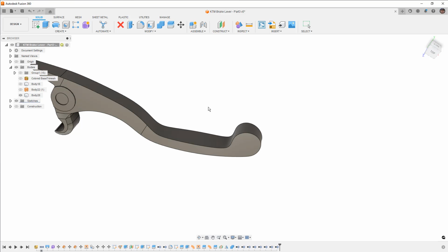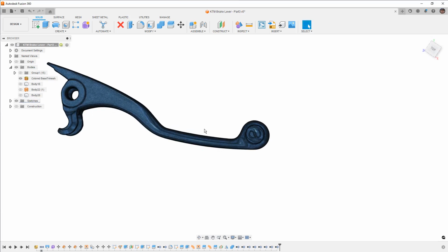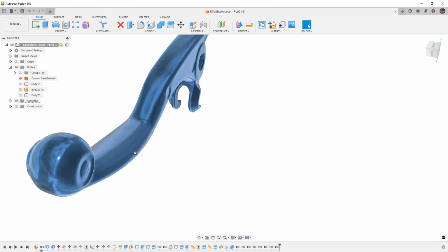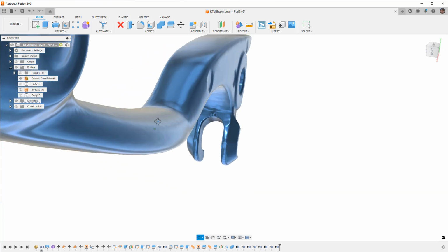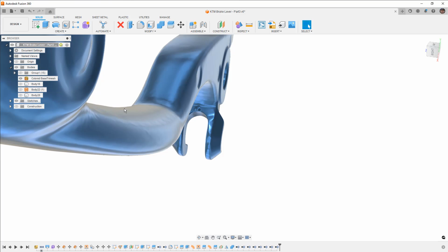And now we need to think about or talk about this front face here. Now on the mesh itself, that front face, which is going to be hard to see, I'm going to do Control and 4 to hide the edges. That front face is rounded. Let me rotate it around so we can kind of see. That face is rounded, and we're not going to get that from a fillet. You can almost see that there's a secondary sort of cut that's happening here.